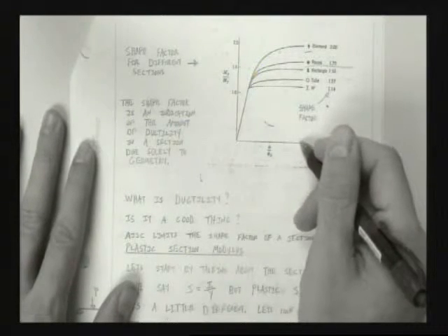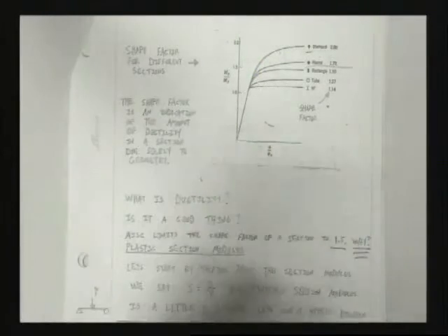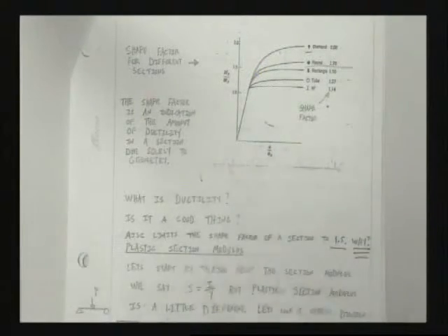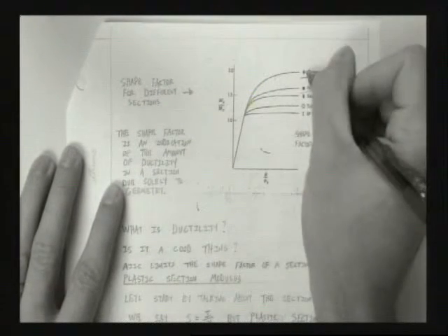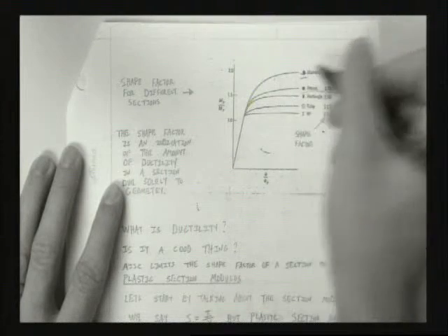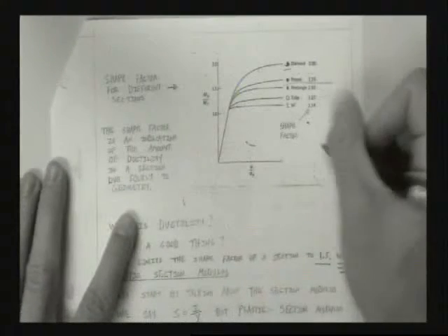Imagine writing on a desk that wasn't stiff, like as you're writing on it, it moves. So there's a lot of benefits of having things that are plenty stiff. Now, what goes on here is exactly what you're saying. There's so much material around the neutral axis here that this diamond is going to start yielding pretty early in its life.